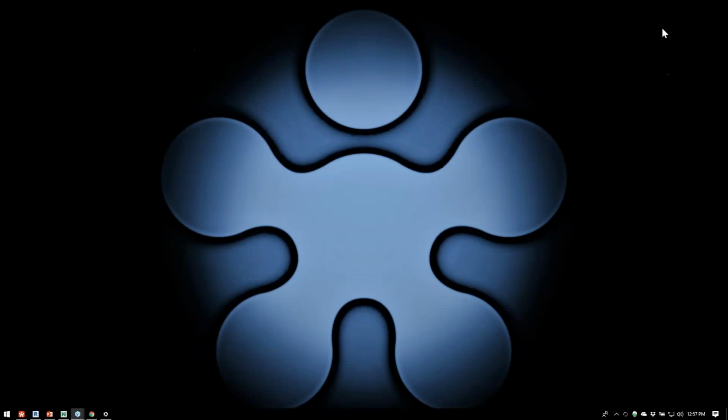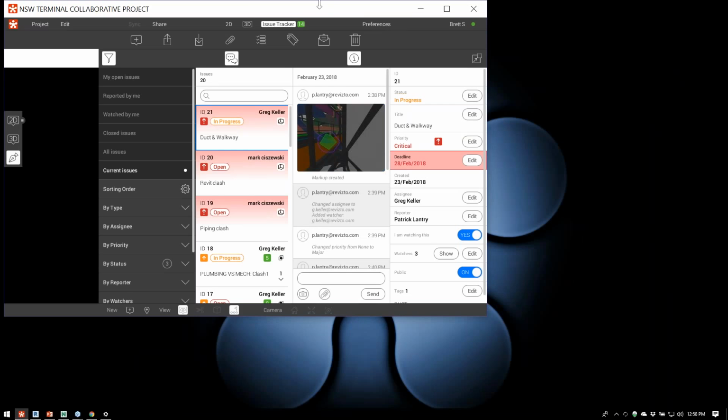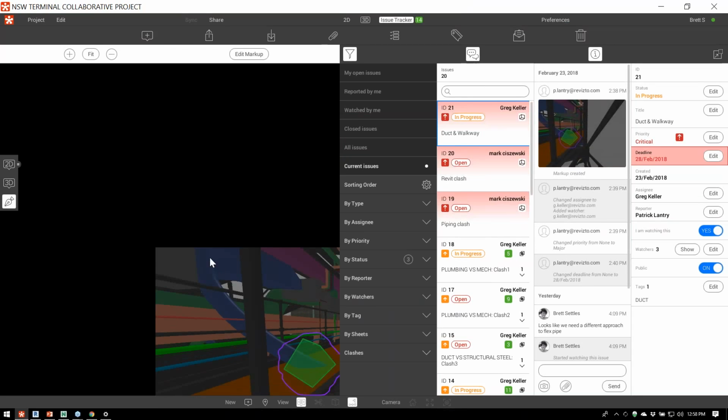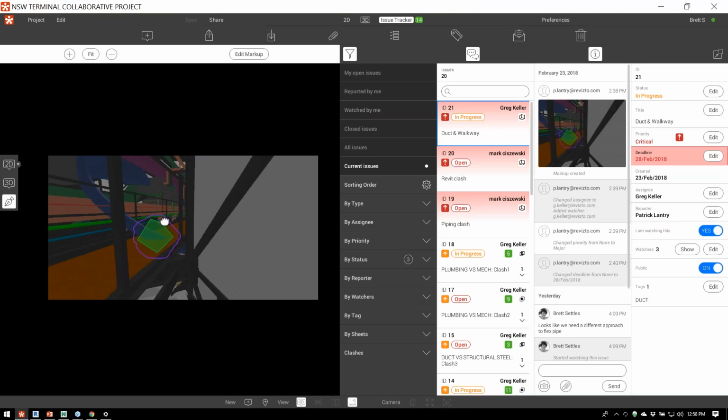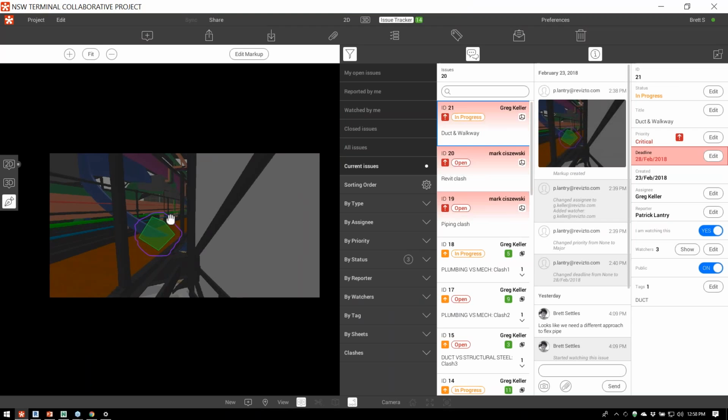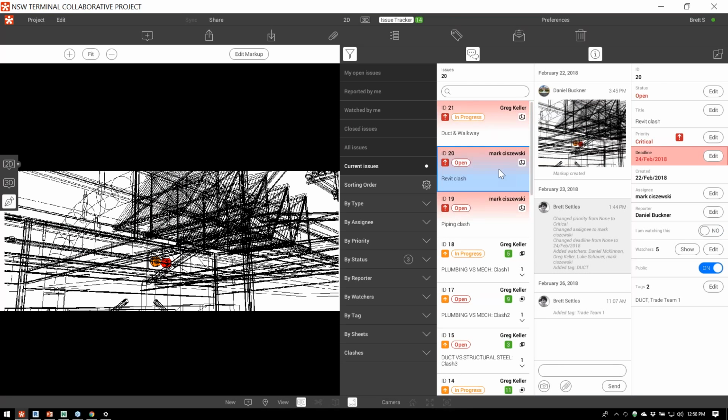So if things change within the actual building information model, those need to be re-exported as an NWF, or some of those viewpoints now become irrelevant or out of date. So Brett kind of touched on that earlier. With Revizto, when you make those changes, the information lives in the location of the XYZ coordinate, not the actual file. So we're never sending the Revizto file. The issue tracker is always updating in real time. So that's the biggest difference between Revizto and Navisworks.